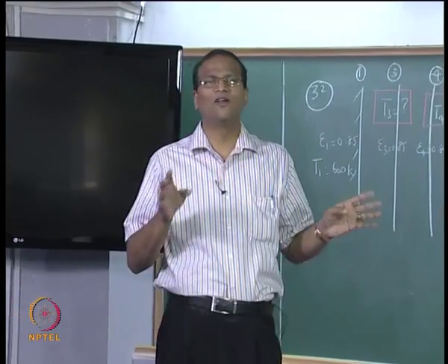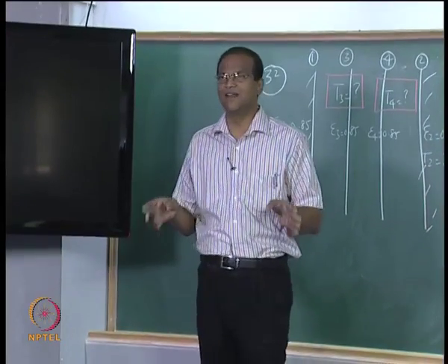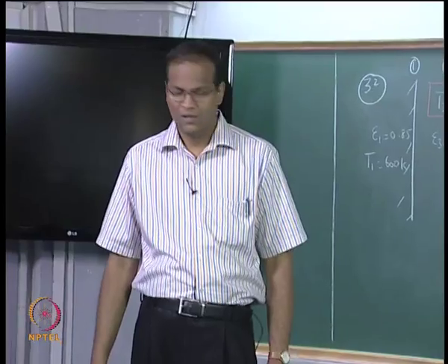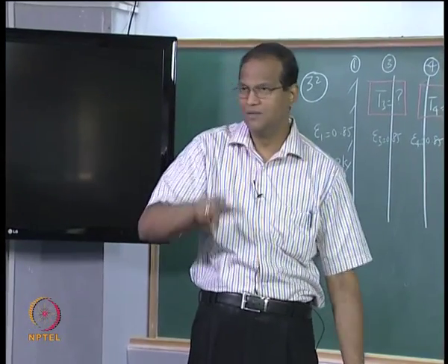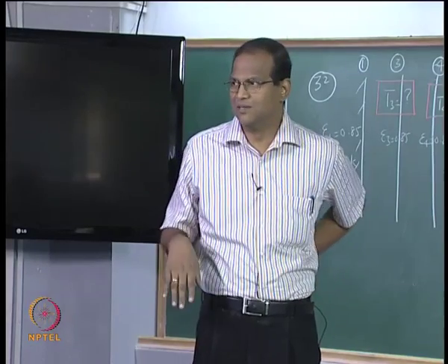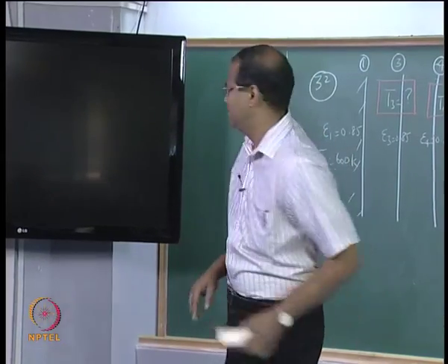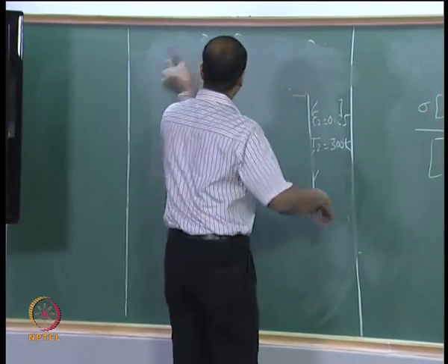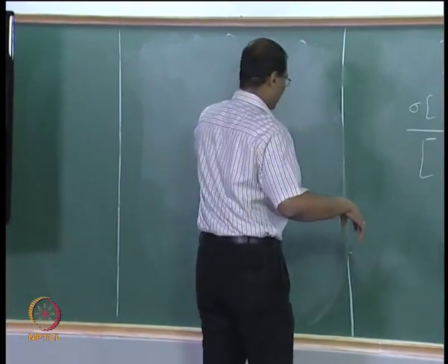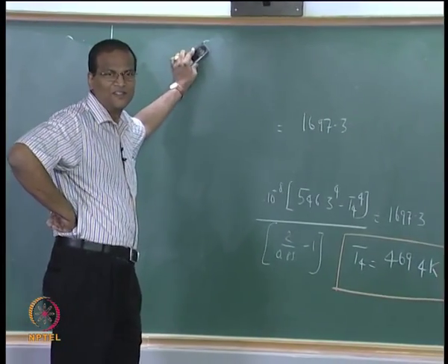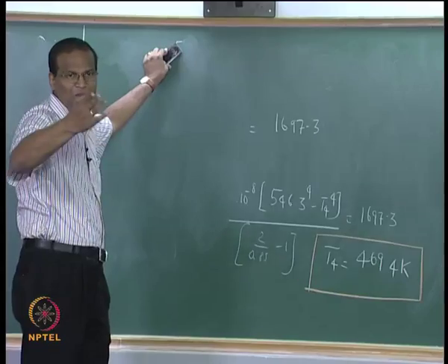So in fact, the radiation shields are re-radiating surfaces. If you consider them as one body, because they have only one temperature, the temperature or radiosity must be independent of the emissivity. That is what we derived in yesterday's class, right.